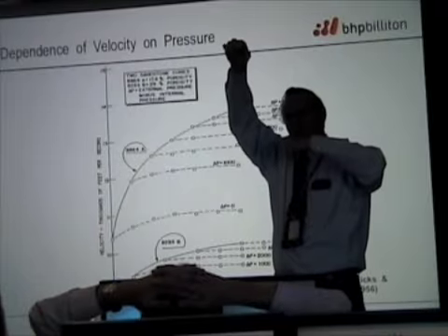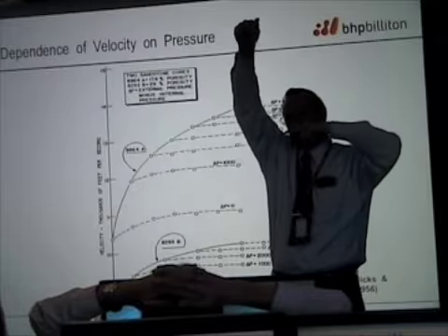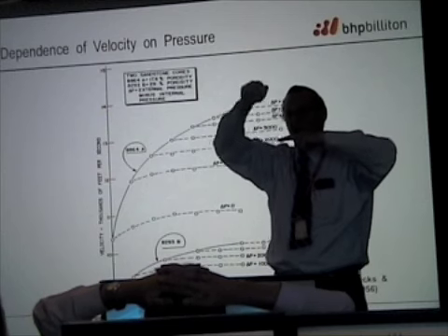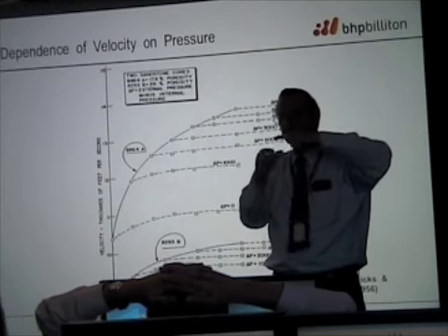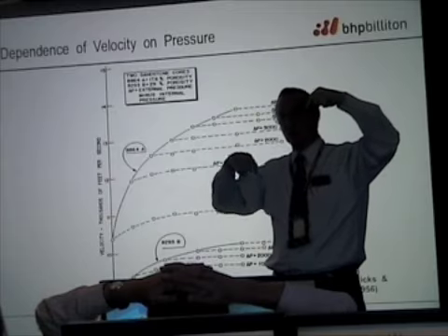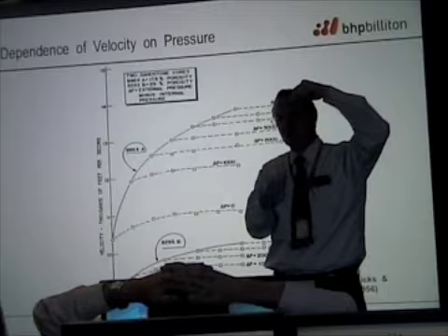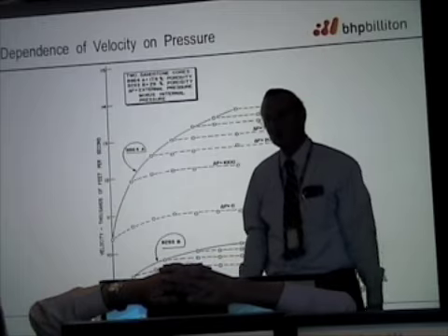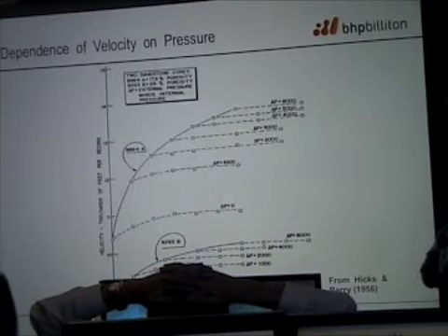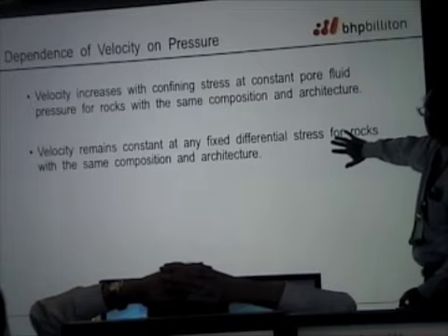It takes a lot of time screwing around. That's what we do in physics. So you now have an independent control. Just put a valve on it and a pump. An independent control on the pore fluid pressure, the pressure of the water inside the jacketed sample, and a pump that is controlling the hydrostatic fluid that surrounds the jacketed core with its two end pieces. That's how you do it. So we already went through that. And it's true for shear as well as P.